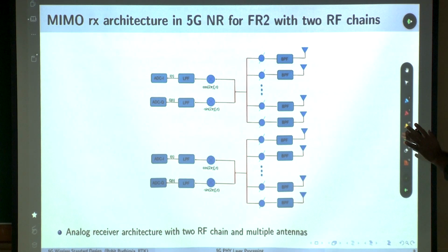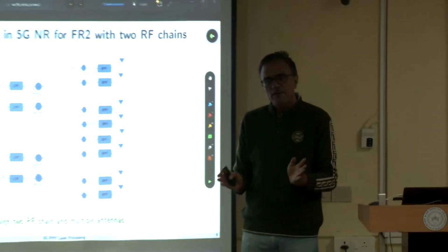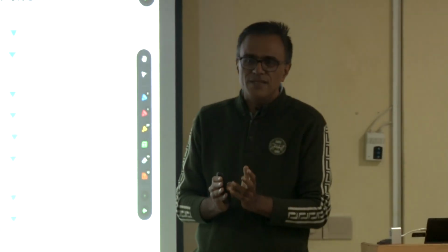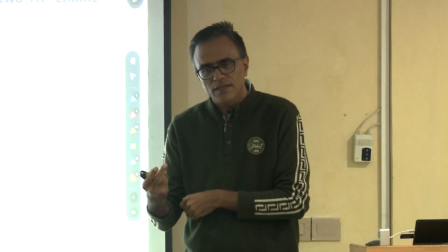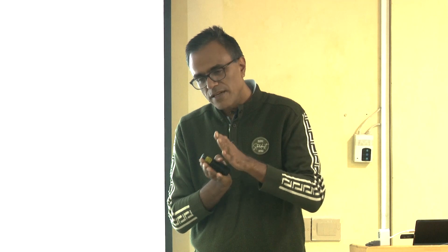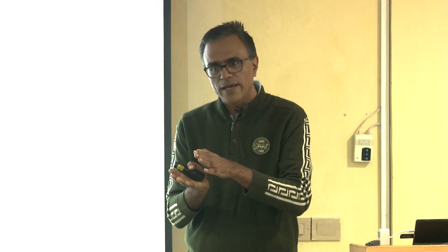So now this brings us to a closure of understanding the MIMO architecture for FR1 and FR2. Our primary requirement for an FR2 system was that it should be much simpler, because you don't have to transmit multiple layers in parallel, given the huge 400 megahertz bandwidth.